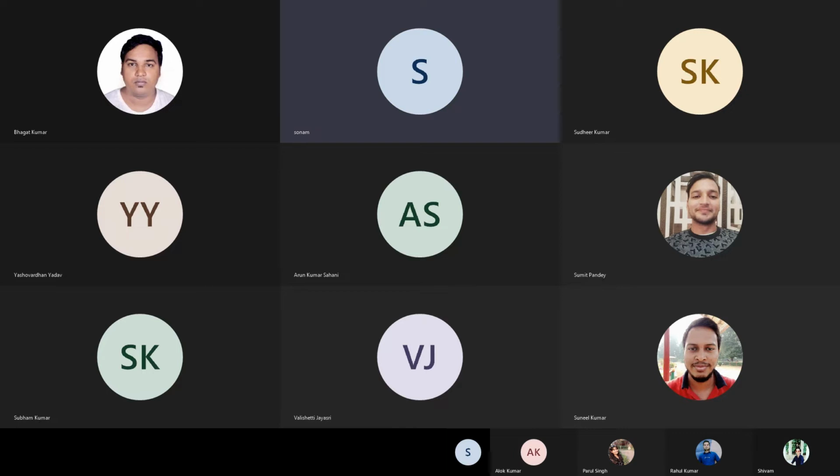Later on, if you want to give the width according to the category, like if you want to give the expressway more width as compared to the main road, and the main road more width as compared to the streets, in that case, you will need one additional attribute where you store this category information. After that, I'm just sharing my screen again. Then by using the symbology, you can assign the color according to it.